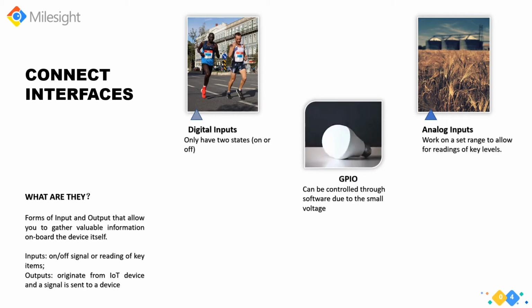And GPIO. GPIO is a type of pin found on our integrated circuit that does not have a specific function. The function of a GPIO pin is customizable and can be controlled by the software. These pins act as a switch that outputs only 3.3 volts when set to high and no voltage at all when set to low.